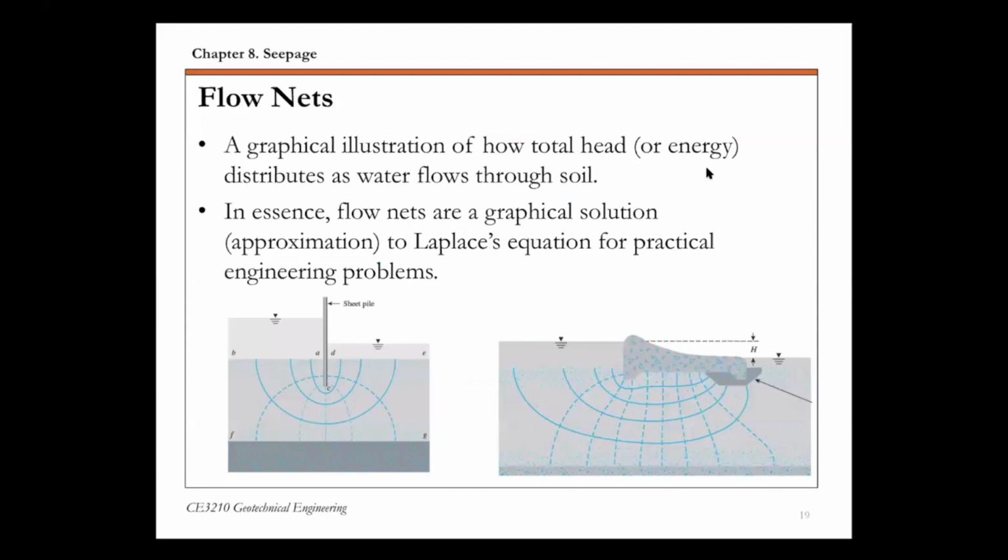First, what are flow nets? As I mentioned, a flow net is a graphic illustration of how total head or energy distributes as water flows through soil. In essence, it's a graphical solution. It's an approximation to the Laplace equation, and it's used for practical engineering purposes.